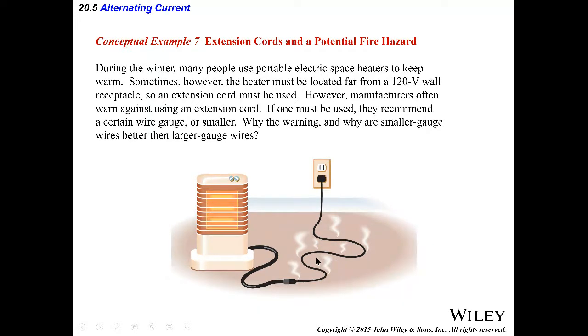Well, if you did not know and you use a thin extension cord, this thin extension cord will have a high resistance, right? And when you have a high resistance, I squared R. Yes, R is now big. I squared is whatever is the current that flows.